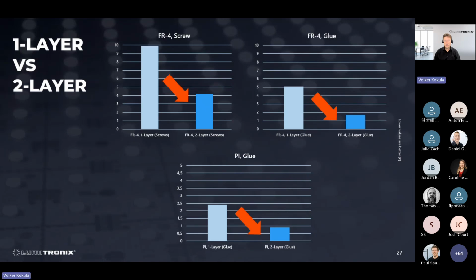And this is not obvious, especially not for the flexible PCB, since the flexible PCB is very thin, and as we have covered before, the efficacy of the heat transfer is not just the base material conductivity, but also its thickness.